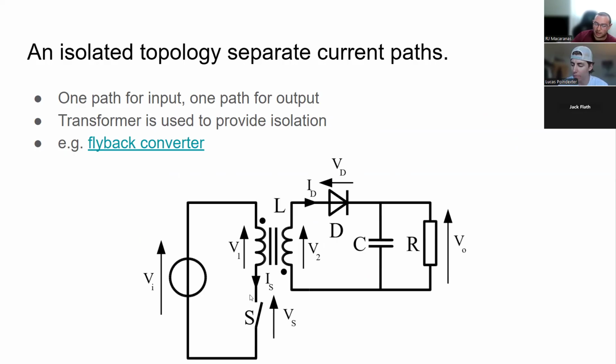So we've got our switch node again, and this is creating an AC voltage across this transformer winding. As we know, straight DC voltage can't be transferred across a transformer, so we need to apply some kind of AC voltage. And of course, this comes in the form of our switch node.